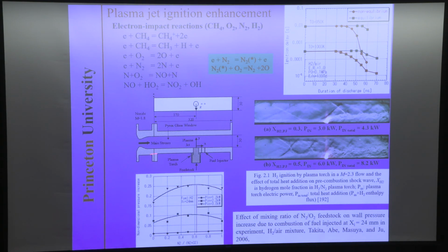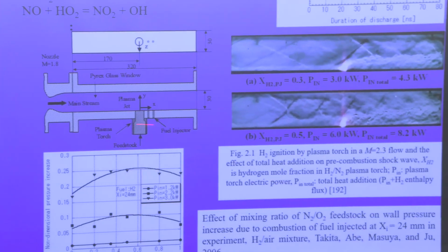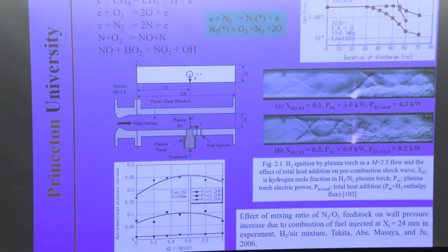So here is a supersonic combustion process. You have hydrogen flowing with air, and you have a plasma torch. As you can see, as you increase the plasma torch, the leading shock wave gets stronger in the channel. This is because of combustion and shock train coupling. You have more heat release, and supersonic flow does not like anyone perturbing the flow rate. If combustion generates heat, that means you have pressure wave generation, and the supersonic flow will form a shock wave to recover the pressure and make the flow go through. Unless the combustion is so strong that the shock wave forms here and propagates upstream, and that is engine unstart of a scramjet engine, right?